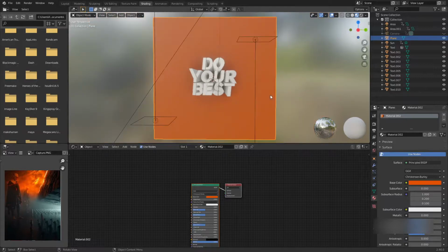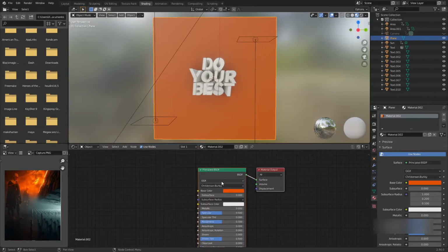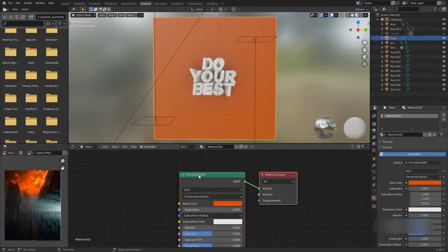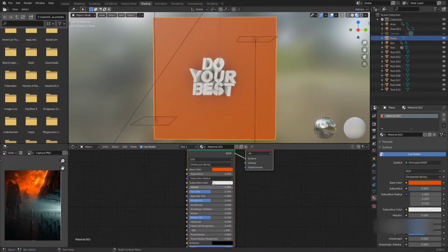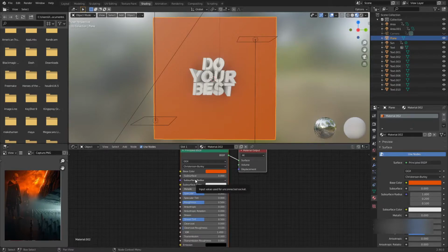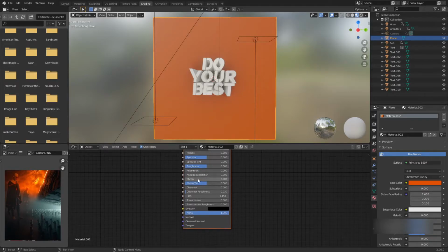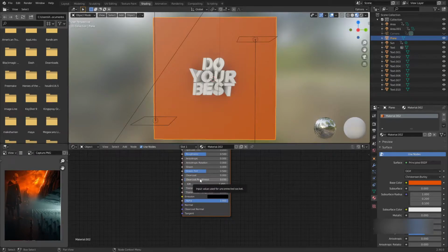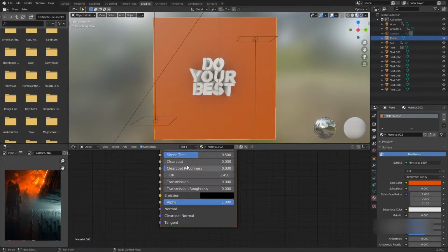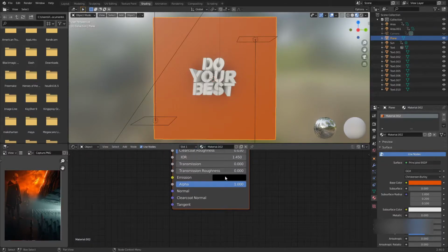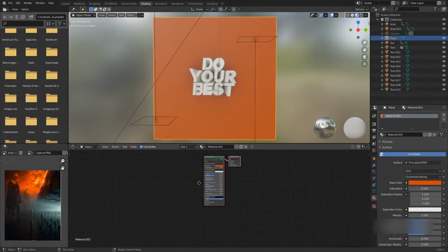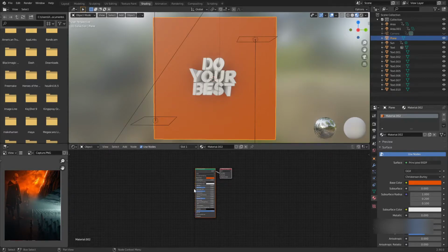So let me just select this plane. As you can see, the Uber shader of Blender is Principled BSDF. So this shader takes care of all the looks inside of Blender, from just a simple color to metallic, shiny objects, plastic, and so on. Then you have your fabrics, clear coat for, like, car materials and so on. Then you have your glass and your IOR settings, your emission, normal, and also your opacity or alpha. So as you can see, you can do a lot with the shader.